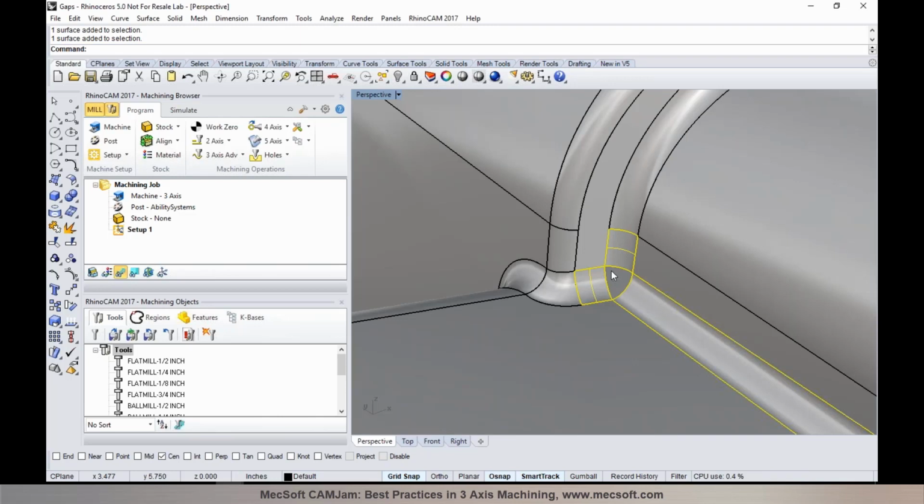But even in cases where you have small gaps or small overlaps, what you're going to notice is tool marks. Because of the gaps, the cutter is just going to dip in slightly and come back out if the cutter is large enough that it doesn't fall in. So at the end of the machining, you're going to see tool marks on the surface. That's why Uday is suggesting that solid models with edge-matched surfaces, or poly surfaces with edge-matched surfaces, are the most important formats if you're very concerned about surface finish. Thanks, Uday. Thank you, Joe.